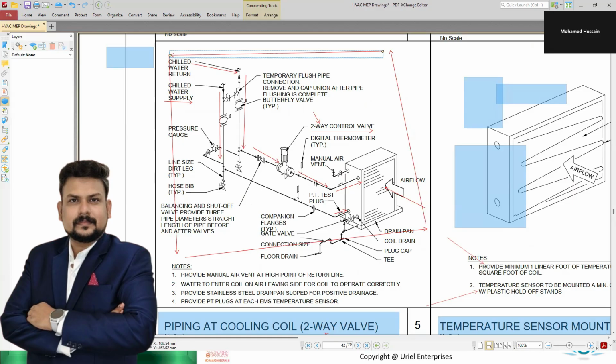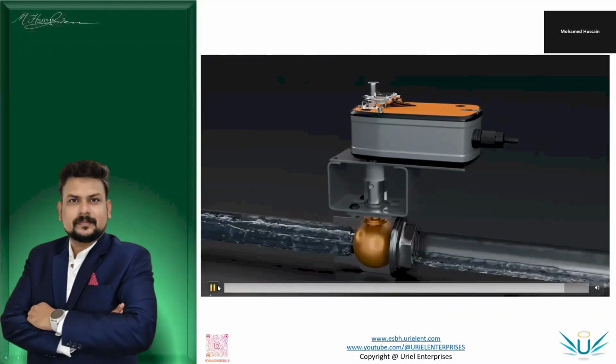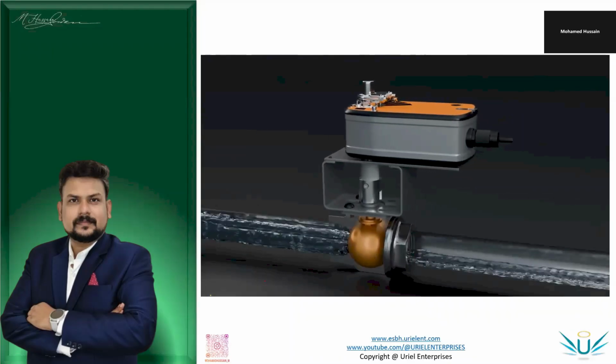Here the control valve alone is dropping that pressure, so that is known as the pressure drop at the valve, versus the pressure drop at the entire system. Using these two, they calculate the valve authority to ensure stabilized control. In this simulation you can understand that entire thing.